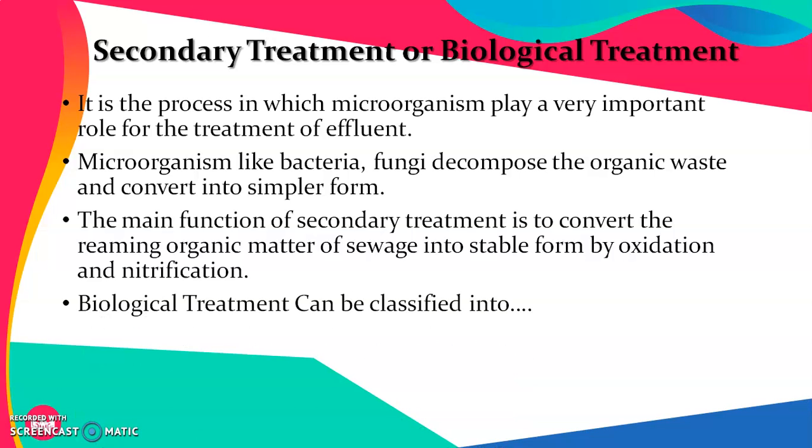Biological treatments can be classified into two heads. One is the activated sludge process and the second is trickling filters. In both of these, aerobic bacteria or aerobic microorganisms are used for the cleaning or degradation of organic waste present in water. In other words, in these processes a very high amount of BOD is removed.